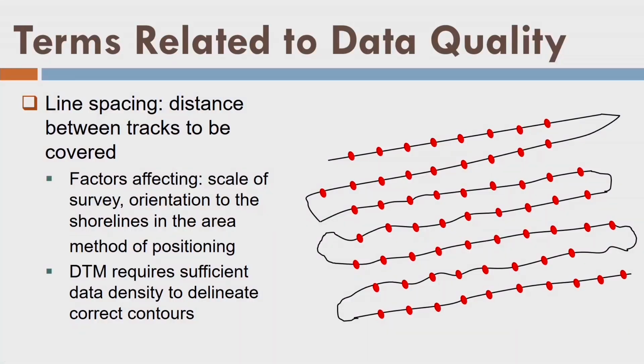I need to have some different instrument, and for that purpose we separate the planimetric survey and the vertical survey in case of hydrography. I hope that you got the idea here. So what do we do? Basically we take a vessel, draw the vessel along a straight line. On this straight line we observe the points at regular interval, a regular time interval or regular distance interval.